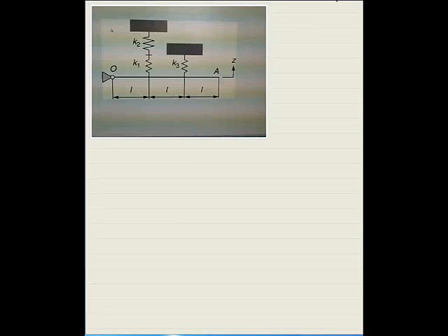Okay, this is problem 2.4, and the objective is to find an equivalent spring that you could locate at point A that's equal to the same as these three springs that are located here. You can use the parallel and series spring formulas that come out of the book.